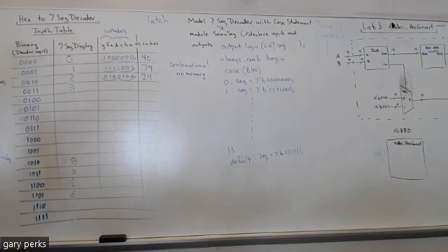Okay, now you'll see when we get to memory in a couple of weeks that when we do want a latch, that's the most common way we'll do it: we'll use an if statement where we don't have an else.